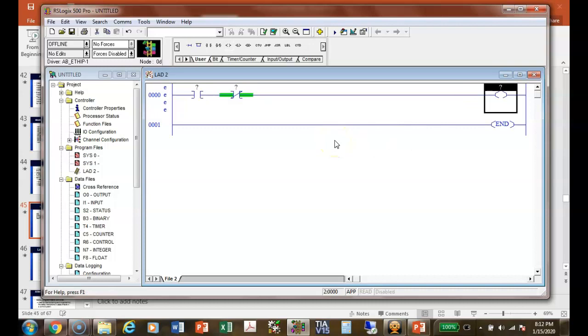Now what I've got to do is assign them addresses, identify which input I'm going to get this information from. This is ladder language, very similar to relay logic, right? We've got two rails, L1 and L2. Input devices are between L1 and the load, and we only have outputs. All we can do is control outputs. What you connect to the output can be anything.